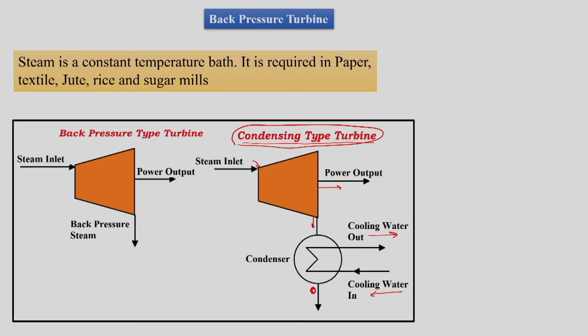In such cases we need wet steam or dry saturated steam for drying or other applications. If we have steam available, we would initially pass it through a turbine, get some power output from the turbine, and in the exhaust give that steam to the required industrial process. We will not let that steam go to the condenser. So we will not have heat released to the atmosphere, but heat going from the steam for a process in the industry.